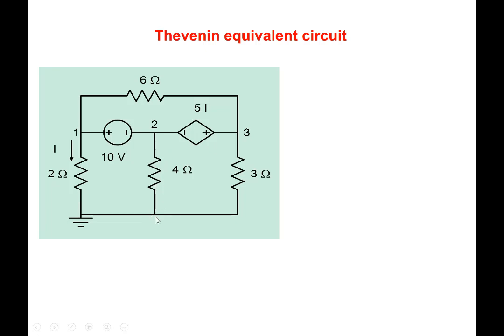Note that when we build Thevenin's equivalent, we'll get the voltage across node 2, but we will not get the voltage across, let's say, node 3, because Thevenin's equivalent takes the rest of the circuit and transforms it into a simplified circuit, which gives us the real value of the voltage at 2, but doesn't give us anything else.